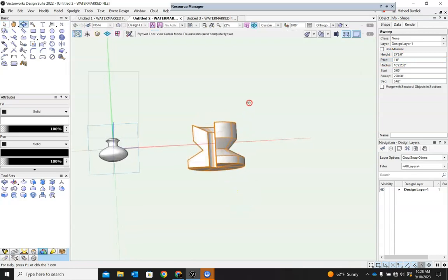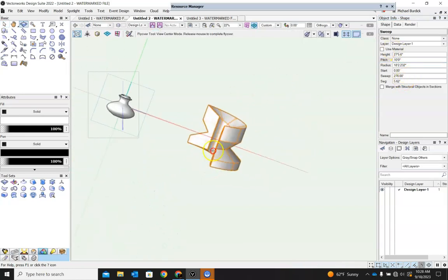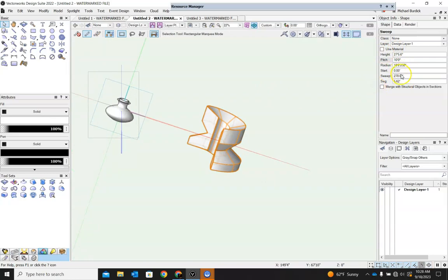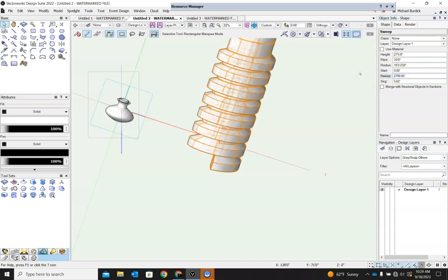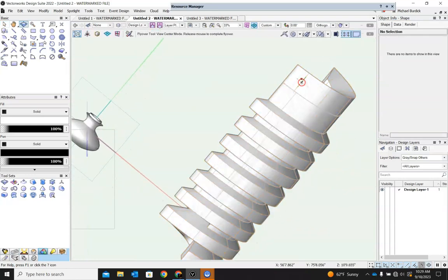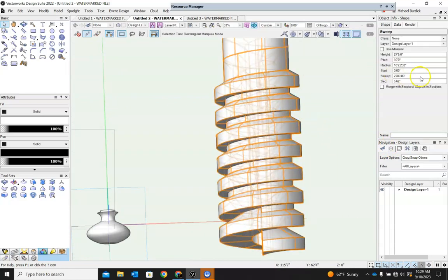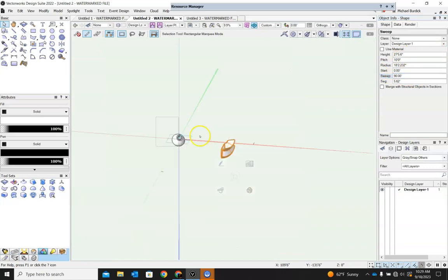It's hard to see again because I'm in such a funky scale. Let's change that a little bit more. Let's change it to 10 foot. So now it shifts as it goes up, kind of creating something of a corkscrew. Let's make this go around many times, and you'll see that creates that kind of corkscrew. So that's something you can play with, is the idea of pitch or the amount of sweep that you're going to do.